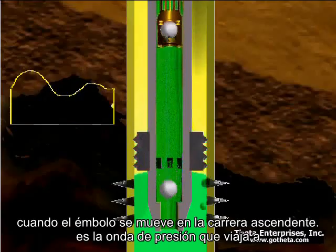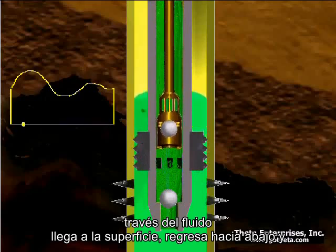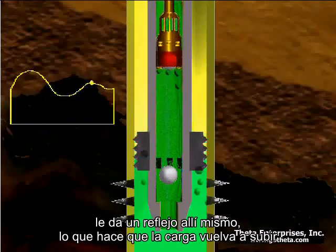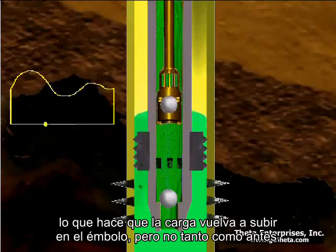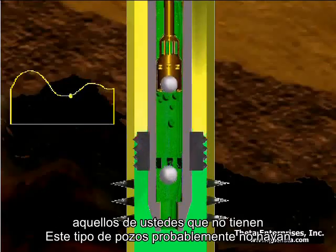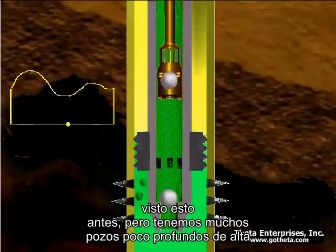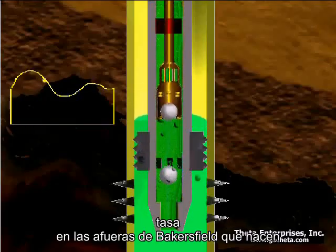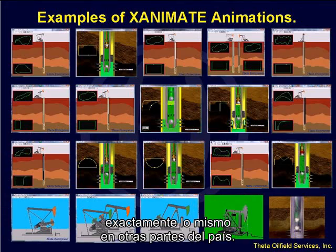That pressure wave travels through the fluid, hits the surface, comes back down, and gives you a reflection right there, which causes the load to go back up on the plunger, but not as much as before. Those of you that don't have these types of wells probably have not seen this before, but we have a lot of shallow high rate wells outside of Bakersfield that do this exact thing, and in other parts of the country as well.